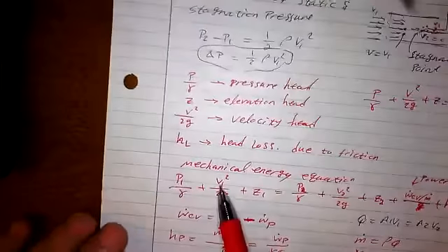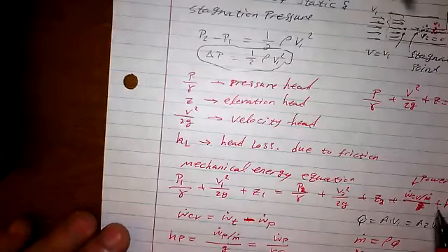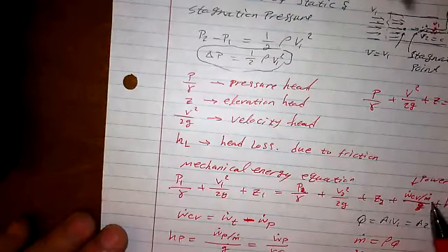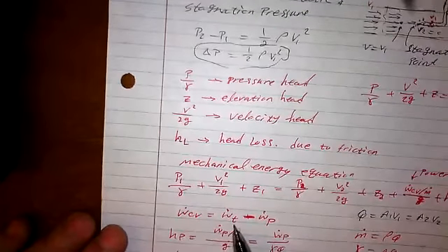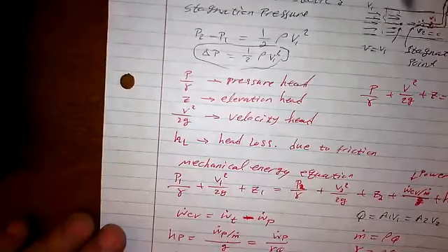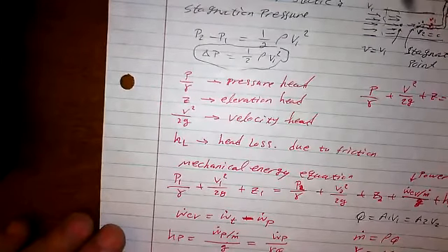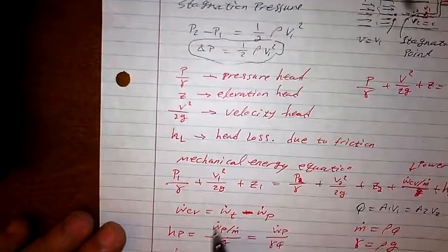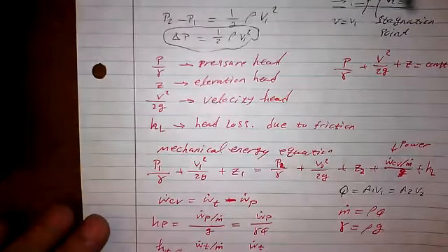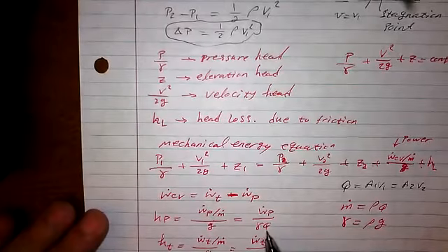And then if you go over the mechanical energy equation, which we have already discussed here, and then if we had the power, which is the W dot CV over M dot, it could be the power of a turbine minus the power of the pump, and then the head for the pump is written as such, or the W dot P for the pump is over gamma times Q.